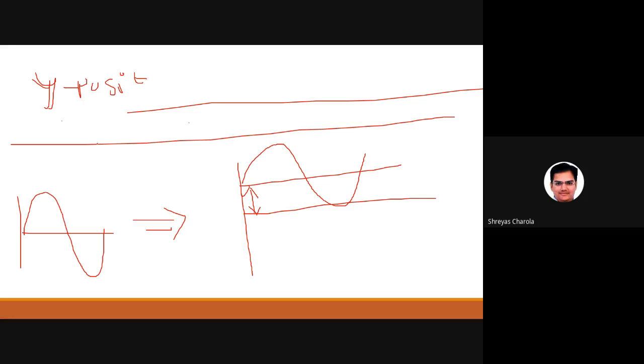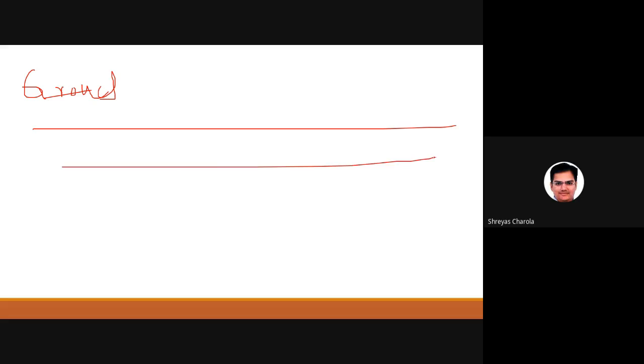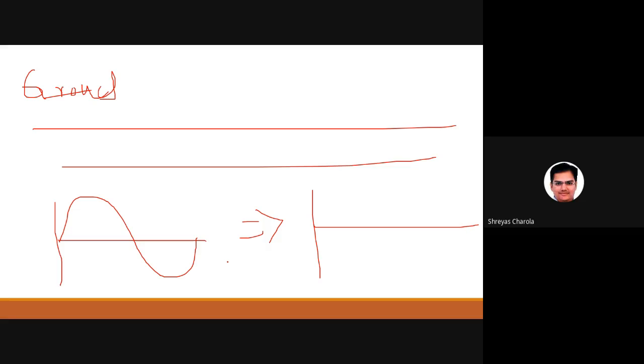What happens for ground? How will you represent that if I press the ground button, what happens? Write a one or two line definition, if you have these signals from a function generator. After pressing the ground button, what should be the output? There will be a straight line, the zero DC line. What is the big deal in this? Is it clear or not?